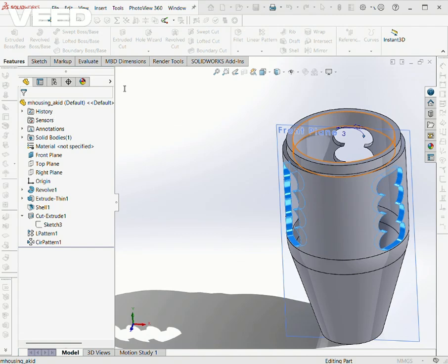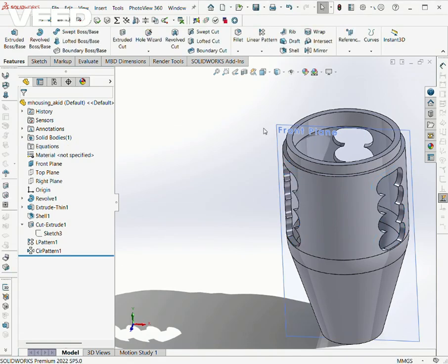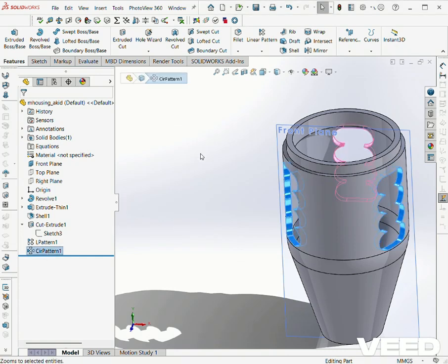In the value slash equation column, type equals 360. So type 360. Now select total instances value 3 in the graphics area. Now this V1 add circular pattern 1 is now added to the equation. Now click on OK to complete the equation and close the box. Now an equation folder has been added to the feature manager design tree. Now to add, delete or edit an equation, just right click on the folder and select manage equations.